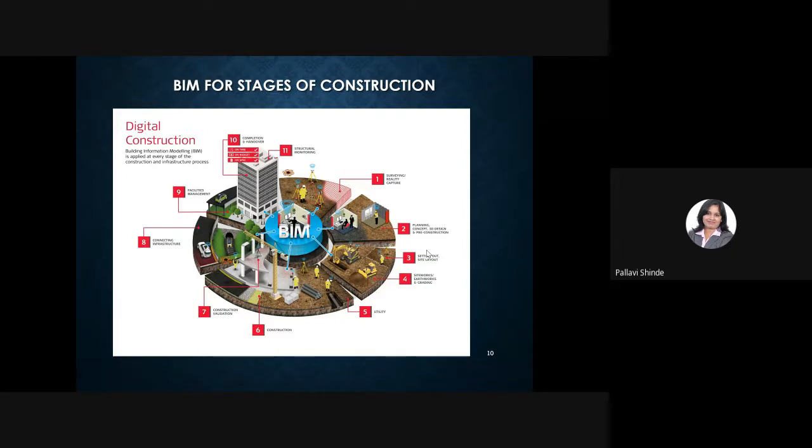So to brief you, what is a BIM execution plan? BIM execution planning is a document which is prepared before any critical BIM project starts. That document states the number of consultants who are going to work on this project. It also states the milestones and the usage of software, which software you are going to use for this particular project. Then even the data flow, like suppose an architect is starting the design, then what is his cutoff date or milestone to give it to another consultant, all the data flow is mentioned in that. And also some plus minus things, like we can exclude these quantities, we can give you this quantity.